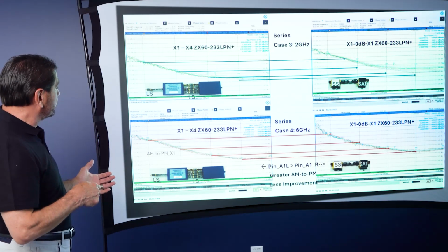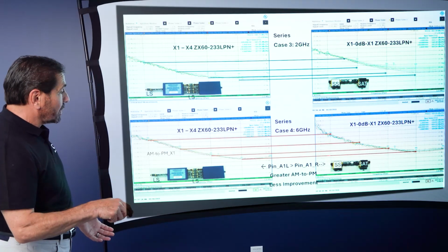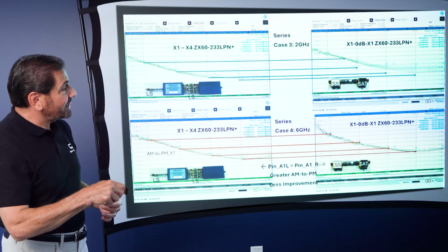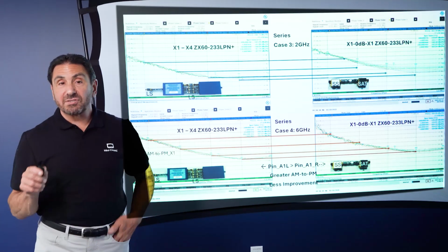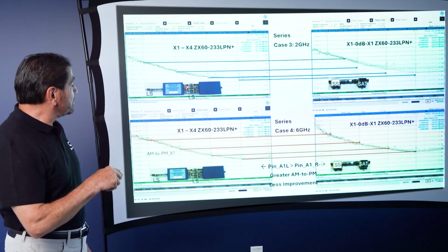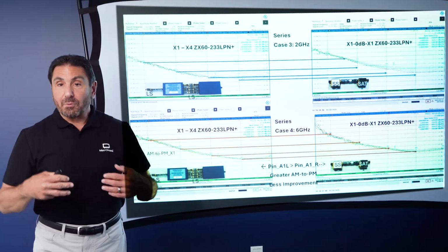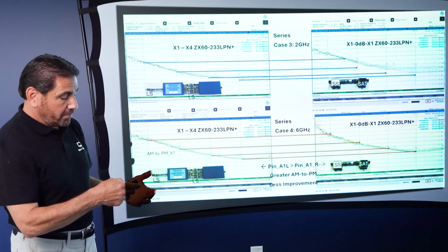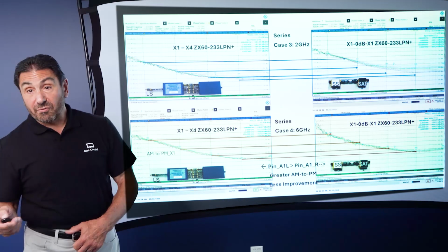One more comparison here. Apologize. 2 gigahertz versus 6 gigahertz. We're comparing against what we did earlier with the 2 stages in cascade, again with the 0 dB pad here. So at 2 gigahertz, look at this. This is really insightful because you are getting much better performance, 1 driving 4 versus 1 driving 1. So this is good evidence that we are in fact improving our 1/f noise by combining, using the 4-way combiner here. Look at that. That's a big improvement.